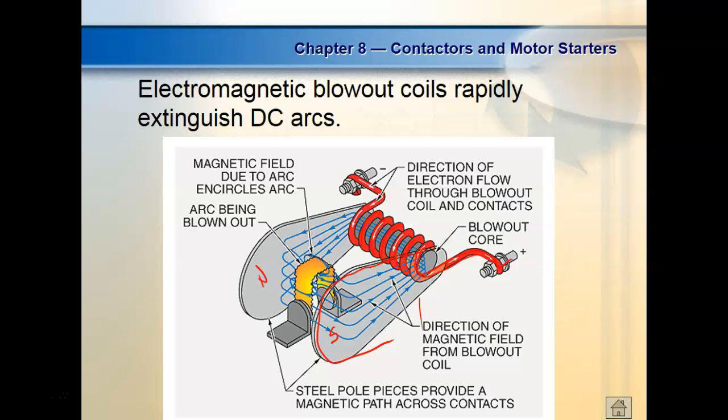Yeah, control. If we increase the field, the motor slows down, but it creates more torque. And if we increase the current going to the armature, the motor speeds up. So not only can we control the speed, but we can also control the torque of a DC motor. And they did that out at U.S.